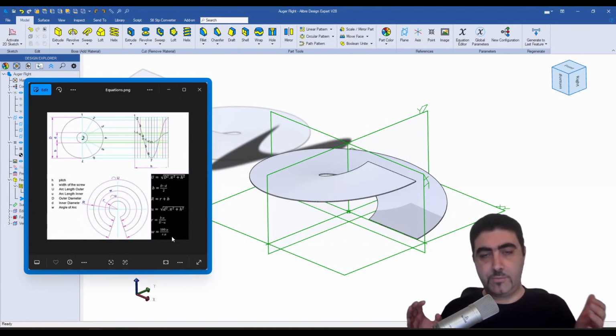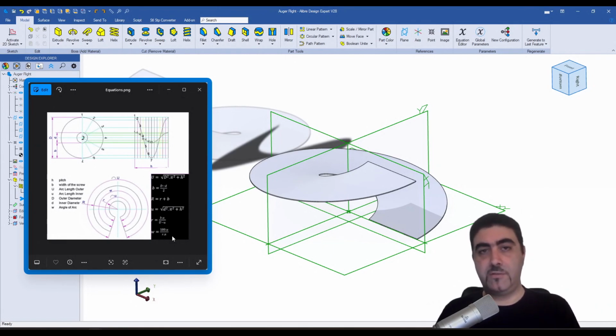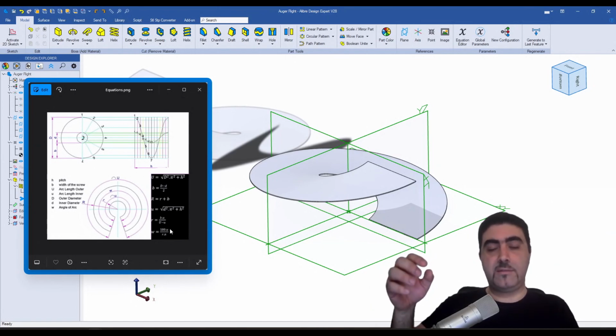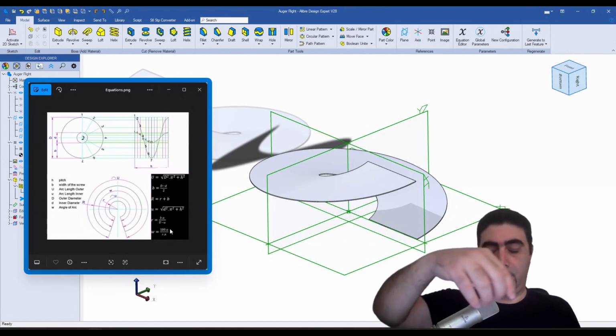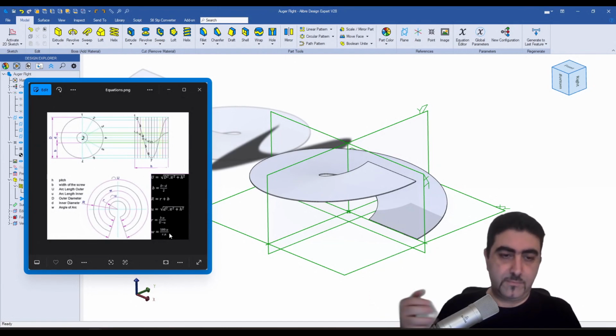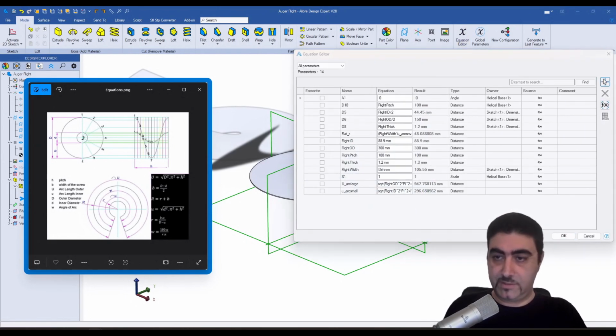That's just saying that on the bottom you have the entire perimeter of the inner cylinder, and on the top you get the arc length, right, which is the portion of the perimeter you're actually using, and then you're multiplying by 180 just to make that degrees, because the CAD system understands degrees, right? So let's go plug that in as well.